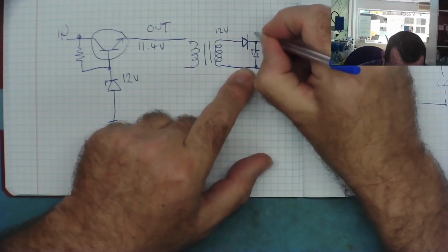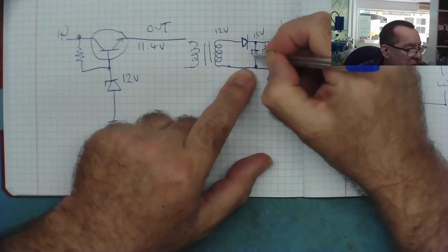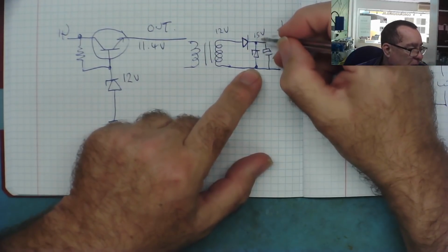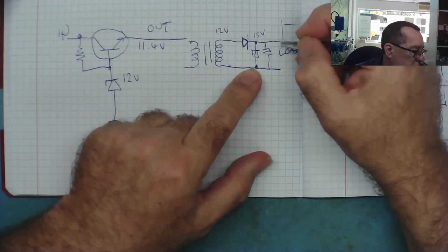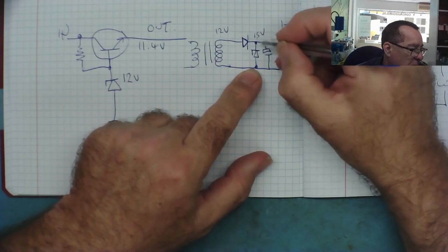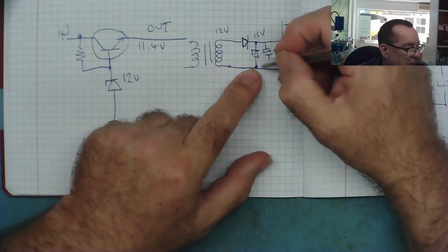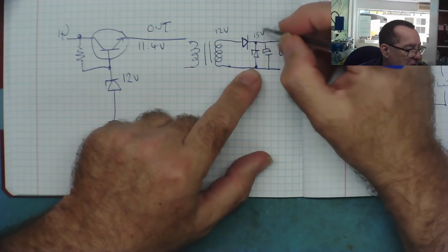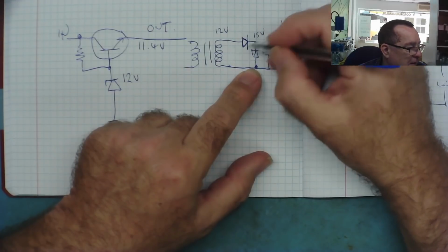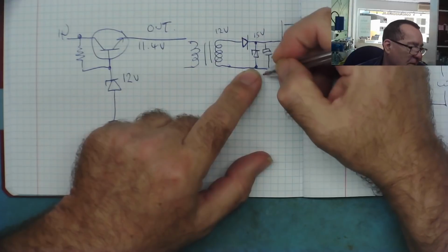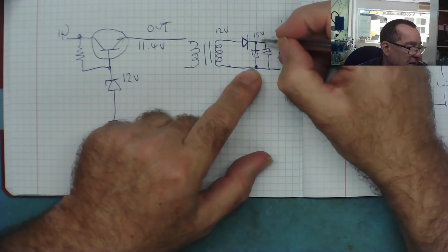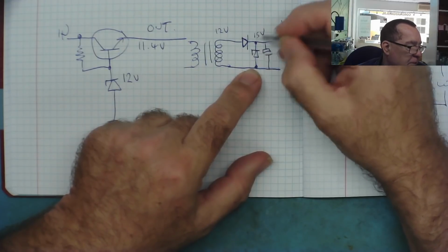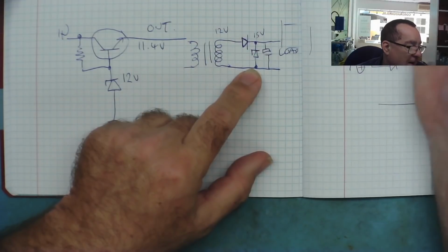This might be set to be using a 15 volt Zener. So in normal situations there's 12 volts across it, there's never more than 12 volts across it, so it doesn't actually do anything normally. It only does something if, due to some fault condition, the voltage here goes above 15, in which case this will clamp it to 15, it will stop it going any more than 15. If a lot of current is flowing, this will probably go short and just short it out as a protection device, so you see that.